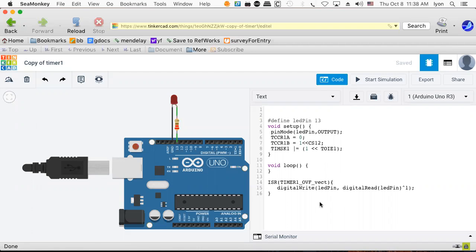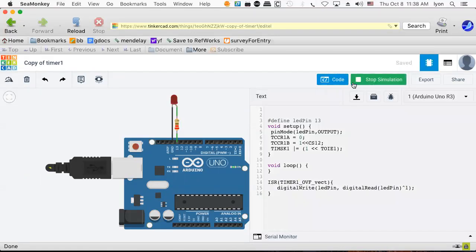And now we can make an interrupt service routine out of blinking the LED. And so then, this is what it did anyway when we did a delay. Only now we can do whatever we want to in the loop, even nothing at all. And this will wake up every second. And it will read what's in the present digital pin, use exclusive OR to invert it, and then write it back out. So in principle, this should blink, I hope. And it does. Look, light goes on, light goes off, goes on, light goes off.